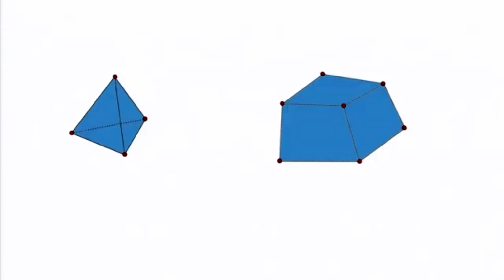We have seen various different kinds of elements in 3 dimensions. These are the very popular elements. At every node, suppose this is node number 1, 2, 3 and 4, we have 3 degrees of freedom like this, and this. These are all 3 degrees of freedom at every node. So if you have a tetrahedral element, then the size of the stiffness matrix will be 12 by 12.